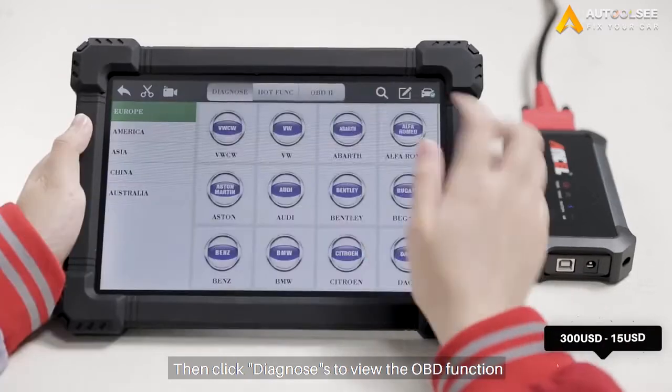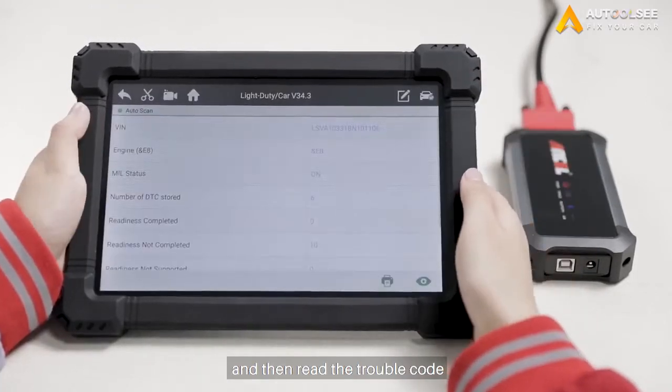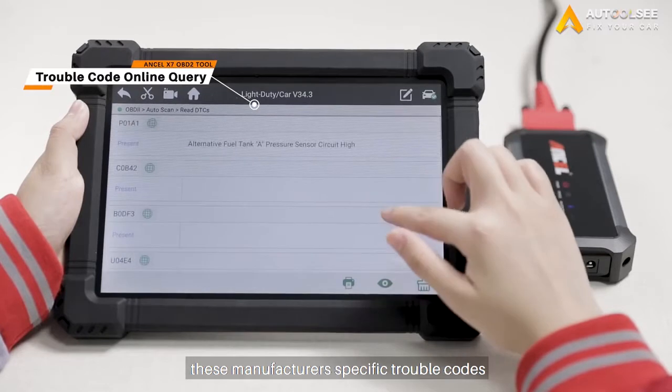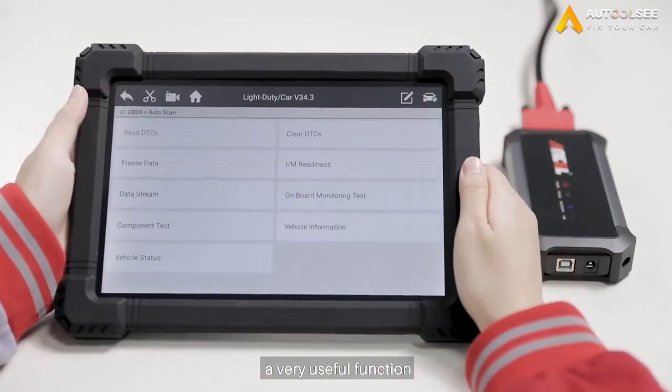Then click Diagnosis to view the OBD function. First, it will automatically read the car VIN, and then read the trouble code. You can see that it will directly display the meaning of generic powertrain trouble codes. These manufacturer-specific trouble codes can be queried after connecting to the network, a very useful function.